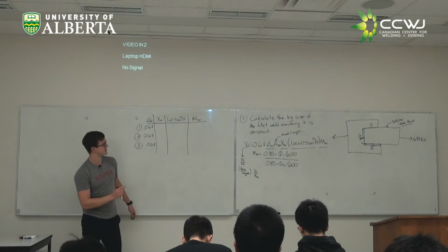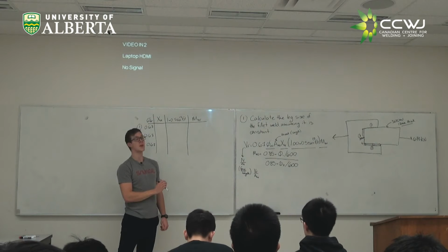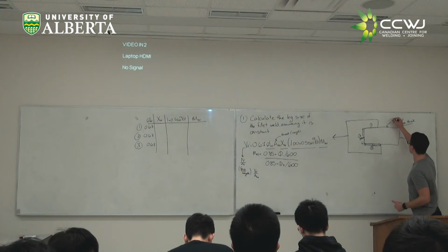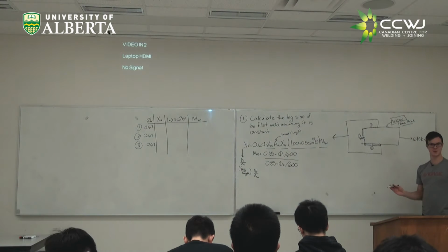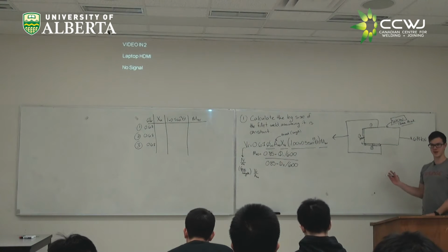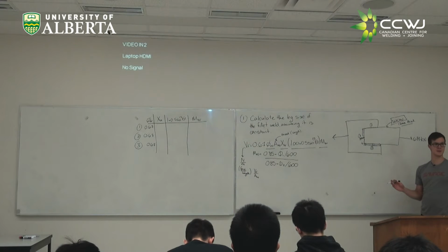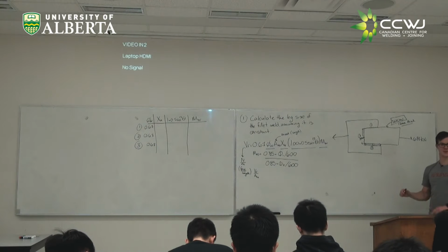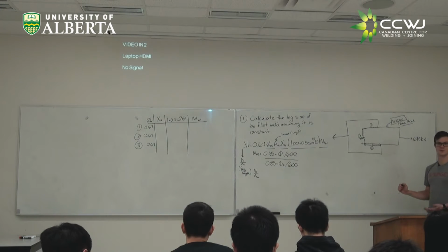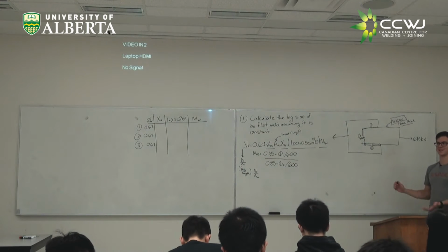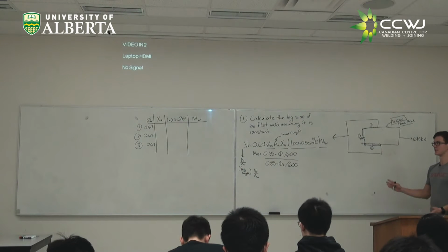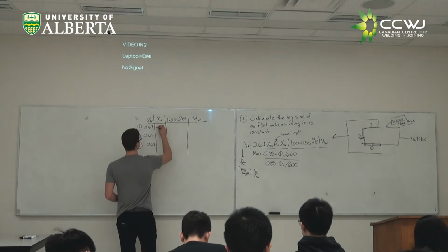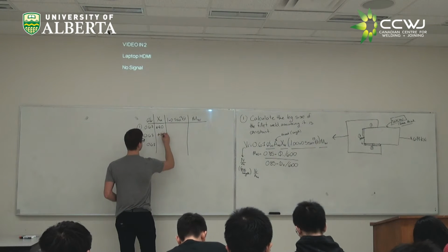Right, yeah, so actually it's a little, I think it's... Not here, like when the professor had the slides on. Right, so we were given here that our material is 300W, so if you go back to those table for 300W, that has an ultimate tensile strength of about 440, and so what's considered a matching filler material is 490 or 70 KSI, so 70, 18, something like that would be what you'd use here. So for this, got 490.